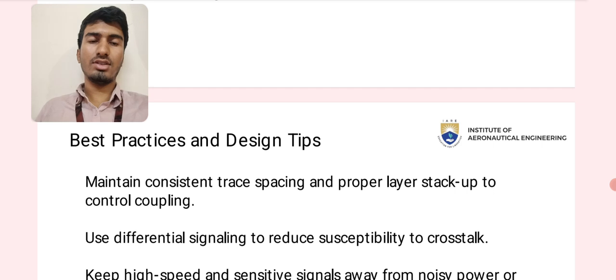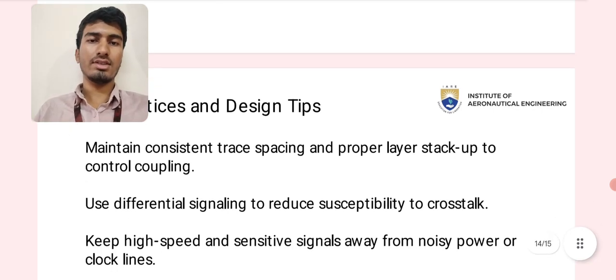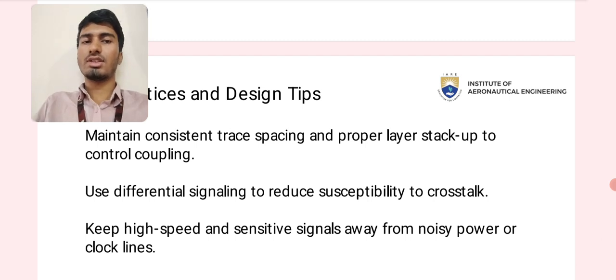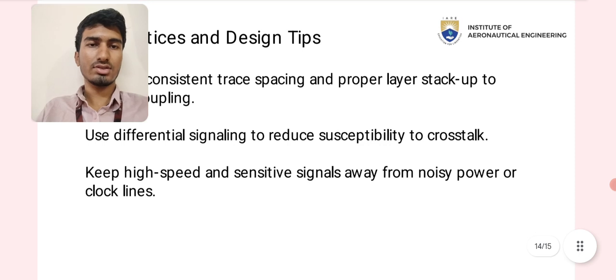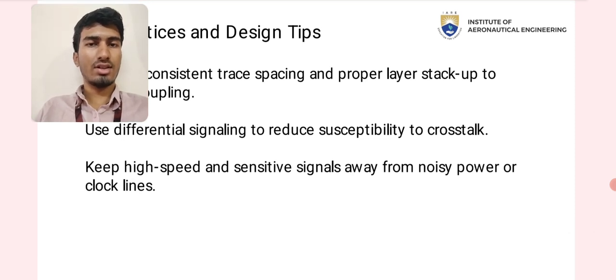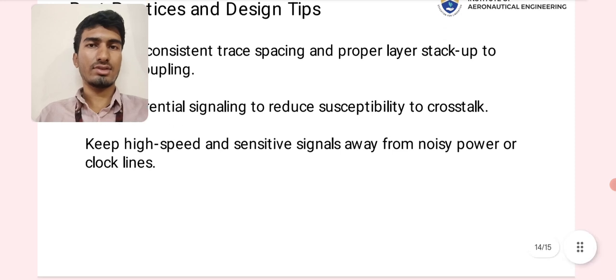Best practices and design tips. Maintain consistent trace spacing and proper layer stack-up to control coupling. Use differential signaling to reduce susceptibility. Keep high speed and sensitive signals away from noisy power or clock lines. To do so, we should keep enough spacing between the two traces of electric fields.